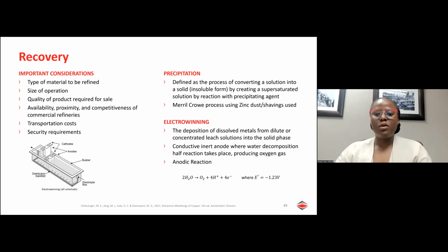Depending on the product specifications, in the case of electrowinning, you can opt to sell the cathodes as they are, or you can further treat your material and generate a gold sludge that is then smelted to produce your bullion. Similarly for precipitation, you can opt to sell your precipitate as a concentrate, or that concentrate can be smelted to produce your bullion bars.